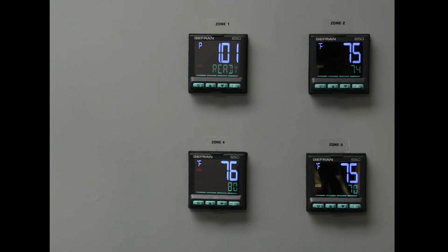Set point temperatures are set in the program. There is also a local set point temperature. If you are manually changing a set point temperature, it is important to understand which set point is being changed. When quick configuration is off and programming is on, options for changing parameters without a password are more limited. This includes the local set point.